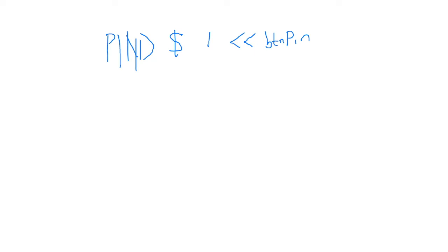Okay, so try not to jump back and forth too much, guys. Data direction register. Okay, so we'll hold on to this. I'll write this at the bottom. So the data direction register, or DDR, sets the direction of the pin. So it sets it as an input or output. And remember, if you want it to be an input, you put 0 in the corresponding pin. If you want it to be an output, you put 1 in the corresponding pin.